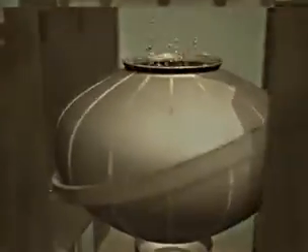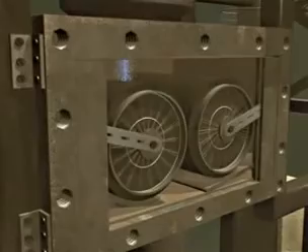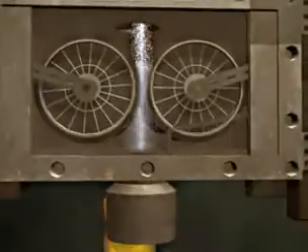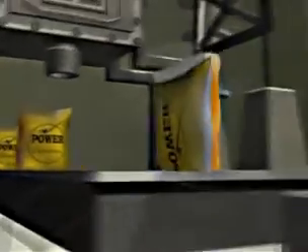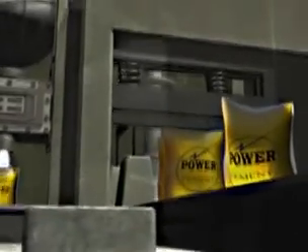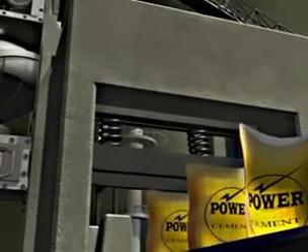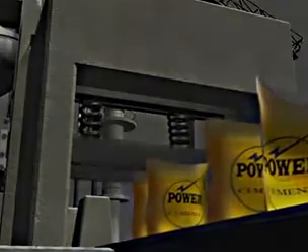The granules are fed into a rotary kiln and heated to 1450 degrees Celsius. Carbon dioxide gas is released and the cement sets into a hard mass called clinker. Finally, the clinker is mixed with gypsum and other secondary constituents, ground into powder and packed into sacks.